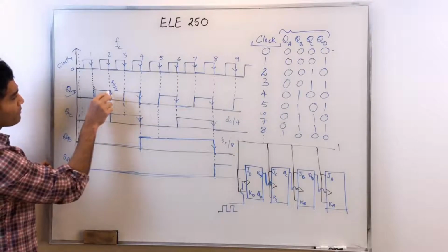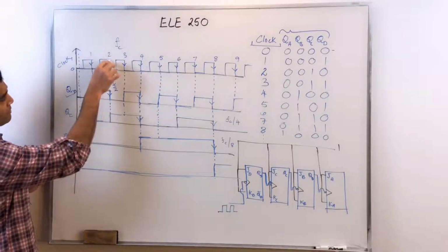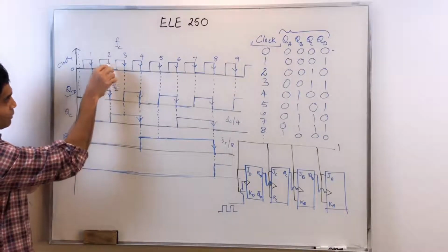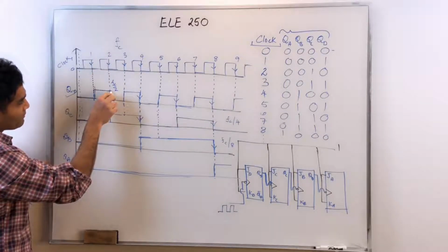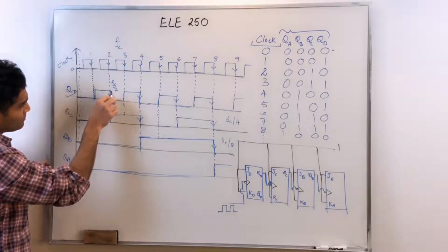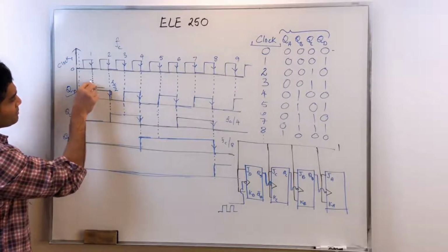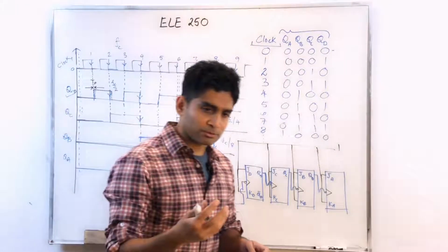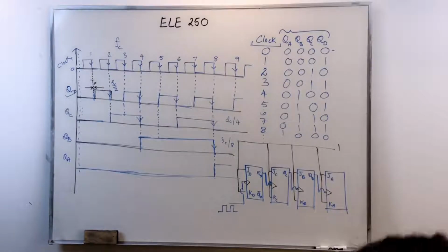So this is going to be my actual output. It's going to be very small for a single flip-flop. Again, the same thing happens here. This is the next active edge. It is supposed to switch exactly coinciding with this active edge, but because of the timing delay, it switches after a slight delay, which we call the timing delay of this flip-flop. Let's say this is TP, the propagation delay of the signal. Are you able to see that? Okay.